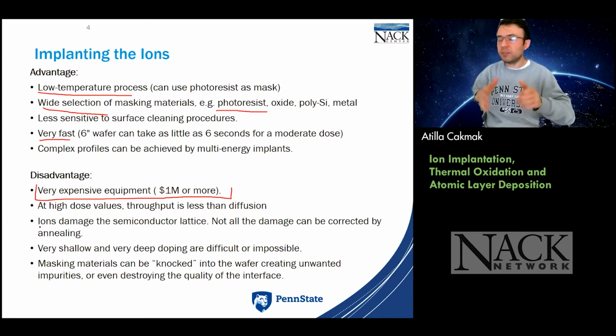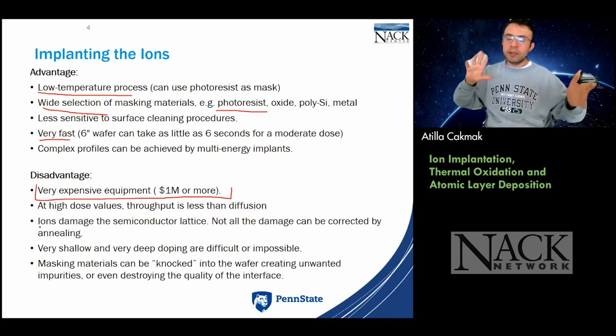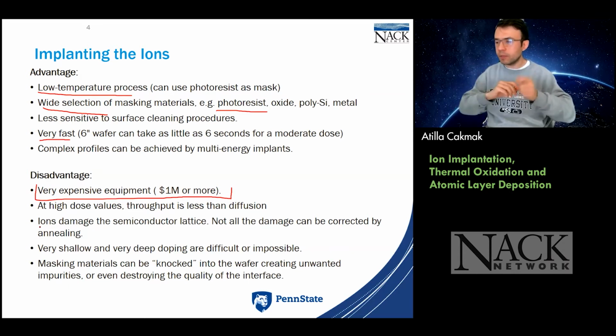But it's really the way to introduce the dopants in a much more professional way rather than the diffusion. But having said that, in our more naive research environment, we're still doing the other methods like diffusion that I just showed you, or spin coating methods that can also introduce the dopants, that we're not going to touch today. But we also have damages taking place in the lattice, right? So we also have to think about how we need to repair the damage. All that needs to be taken into consideration.